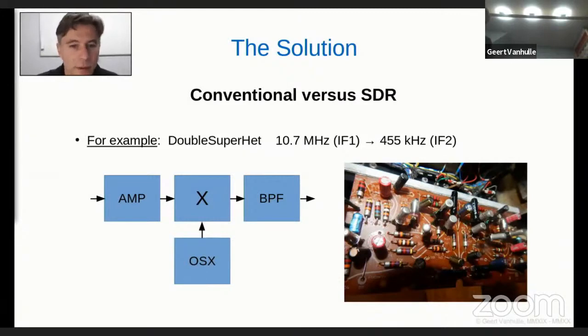Now, this gives us a complete hardware circuit with transistors, a lot of components. It's all analog, so we have to compensate for a lot of things, for temperature, for drifting. Components have, of course, tolerances, and a lot of things can go wrong there. So it's quite an effort to build these kinds of converter stages. If anybody has done this practically, you know that to get, for example, a constant propagation delay, it's not so easy to design a circuit like this.